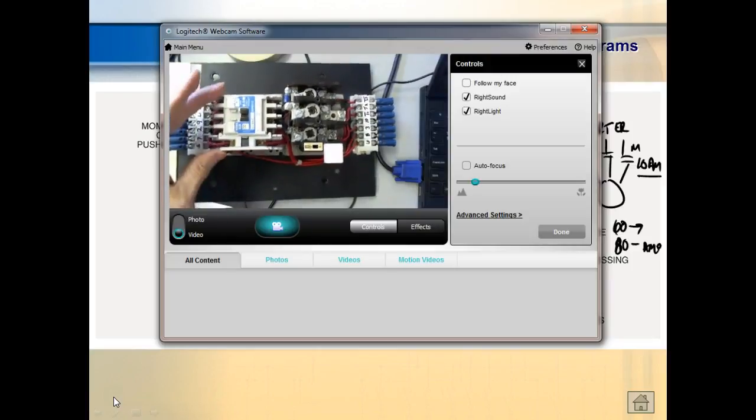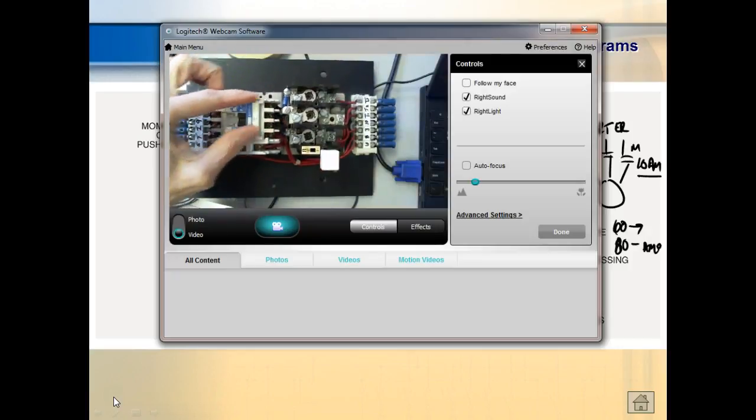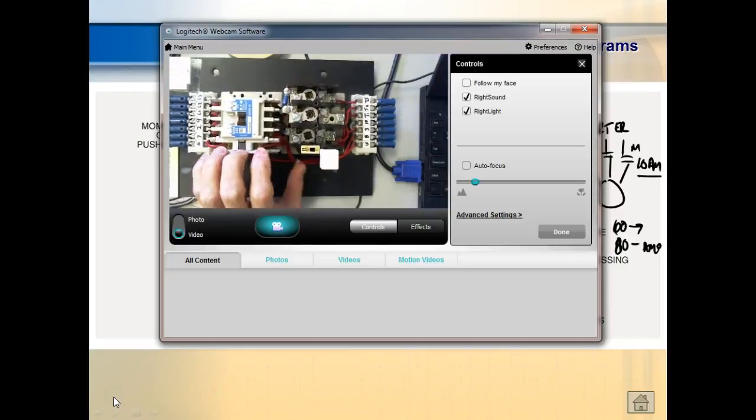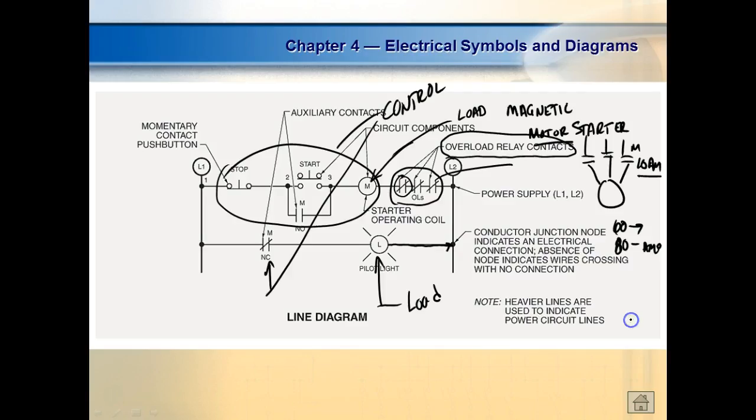has contacts on it. But then on the side, these are our power contacts right here. So these would run the motor. And then over here on this side, we have what we call auxiliary contacts. Auxiliary contacts stay inside the control circuit. Your power contacts are outside the control circuit. Y'all understand that? So normally we have two circuits associated with a control diagram, which we'll eventually get to. We'll have a control circuit, and then we will have a power circuit.